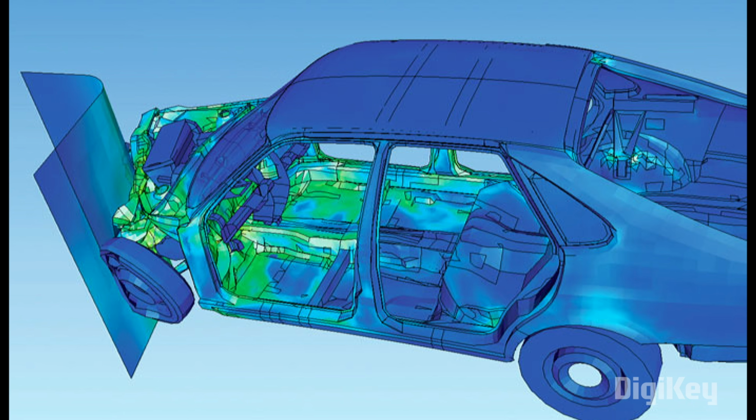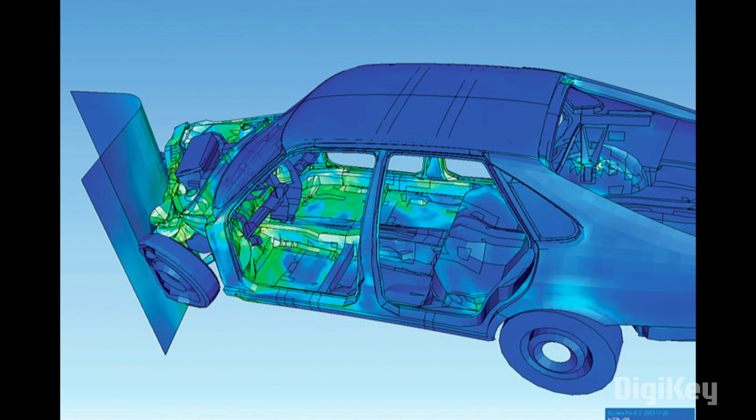For example, engineers use FEM to predict how this car would deform during a crash. I'm not a mechanical engineer, and I haven't studied statics, so I couldn't perform FEA by hand right now. But FreeCAD comes equipped with an FEM Workbench that can estimate the deformation and stress on my bracket design. It can handle multiple solids, electromagnetics, and fluid calculations. But to start, we'll perform static analysis to figure out how a single bracket behaves under a light load. Let's get started.